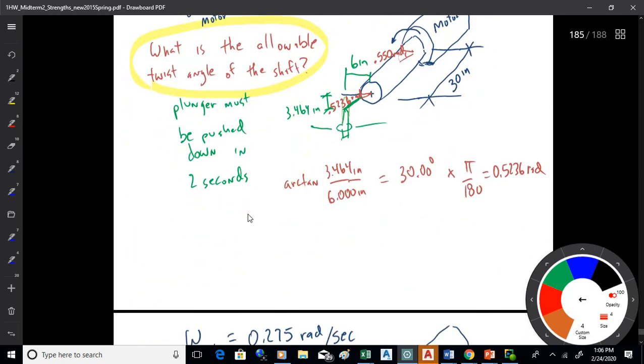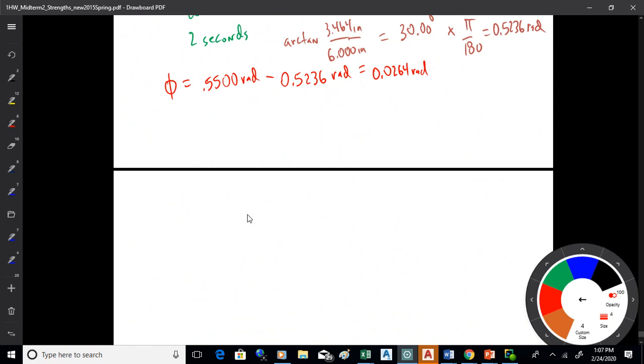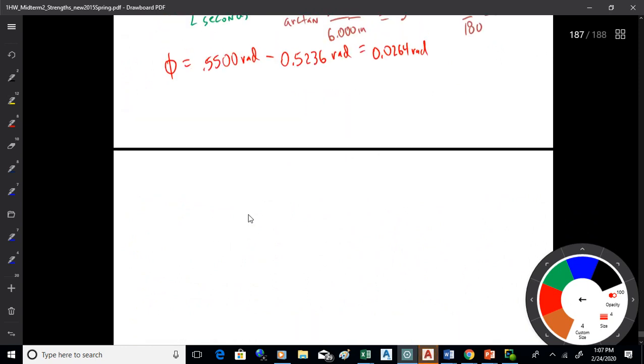All right, so now once you've got that, we've got the difference there, we've got these values to work with, so now you can find the moment of inertia based on those values, and that'll get you to the radius. So what you've got for the angle is phi is TL over IG. So what that means is the torsion then will be phi IG over L. And I'm sorry, we want to get actually the angle.